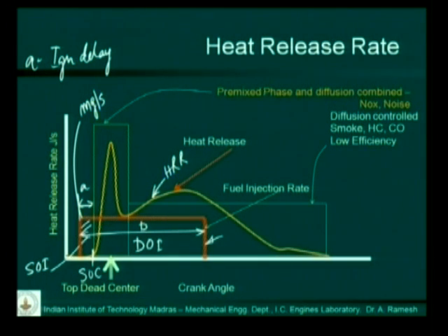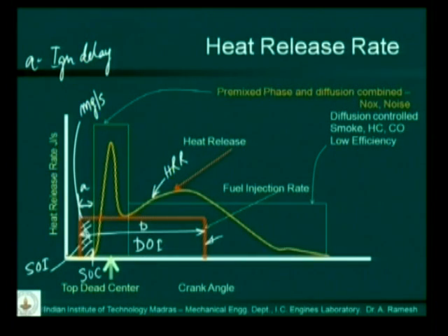So between start of injection and start of combustion there is a lag, but you should understand that during this lag period fuel is still being pumped into the cylinder, and this fuel which I showed as shaded is actually fuel that is being pumped into the engine, but it's not burning. It's simply staying in the engine, mixing with air and forming a combustible mixture. So at the end of the ignition delay period, this accumulated mixture suddenly burns. It is like an explosion. This is what is called diesel knock. Diesel knock occurs just because the fuel that is accumulated during the delay period mixes well and burns suddenly.